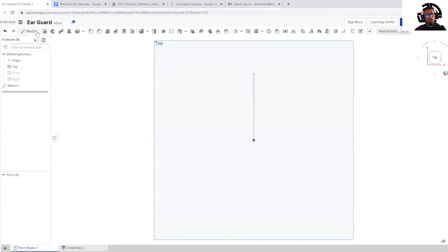So now we're going to be going into the sketch. Right here, I have my first sketch. It may be good to get into the habit of naming your sketches, because once you start seeing sketch 1, sketch 2, sketch 3, sketch 4, you kind of lose out on some detail, and it's not beneficial to you, since you're having to go back and refer to it. We'll take the time to look into it: oh, this is the main sketch, this is a secondary sketch, and this is the sketch with text. You want to make sure that you're easily able to refer to it, to decrease the amount of time that you're taking to do a specific design.